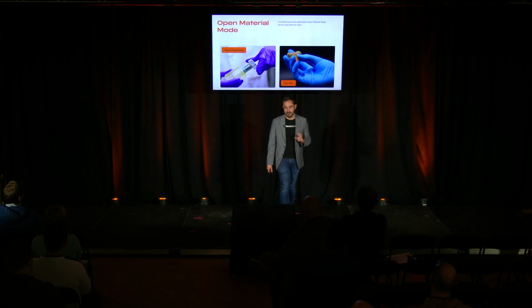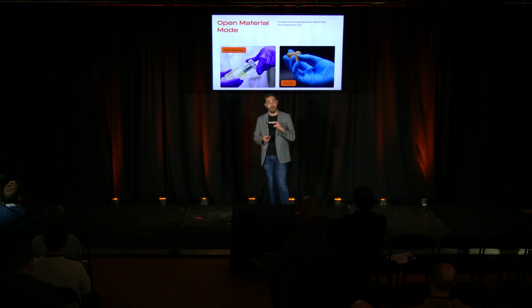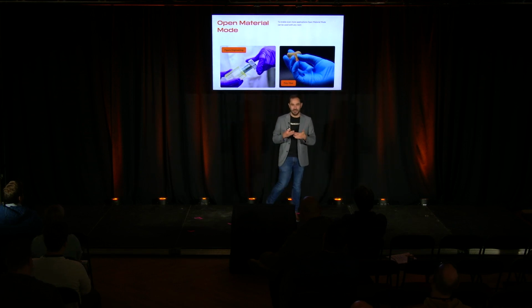I have two really awesome customer examples here. One is from Figure Engineering, and they are printing masks, or masking jigs basically, for electroplating. In this case, this screw is going to be electroplated, but you don't want to electroplate the threads because you'll change the thickness, the offset, the tolerances, and then your threads won't thread together. So the material is specifically designed for that application and what they need for doing that masking.